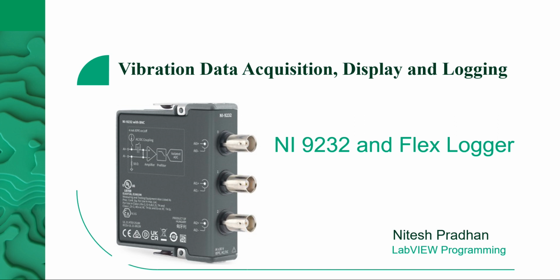In this session, I will show you how we can acquire, display and log the vibration data. For that, we will use 9232 and Flex Logger. 9232 is a sound and vibration module. It is a C-series sound and vibration module which we can use for the vibration data measurement.